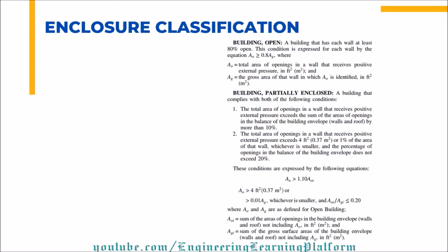The second criterion is that your opening in a wall is greater than 4 square feet or 1% of the area of the total wall, and the total area of other openings in the structure does not exceed 20%. In simple words, the second condition is if your area of opening in a wall is greater than 4 square feet and greater than 1% of the total area of the wall.